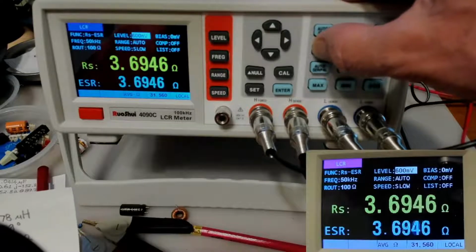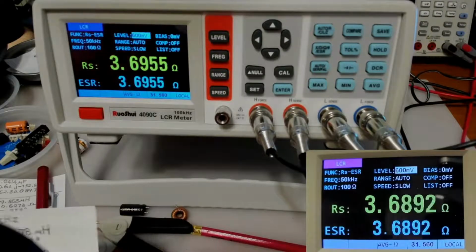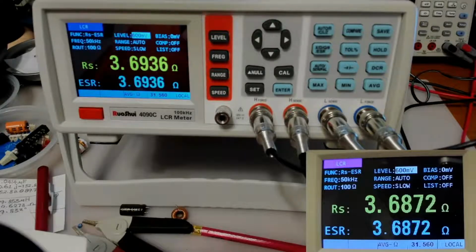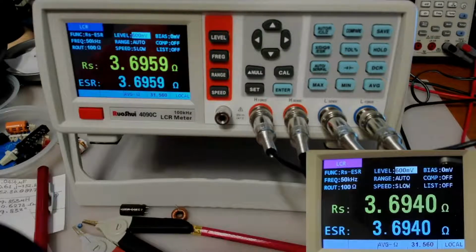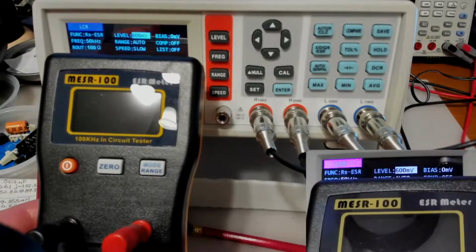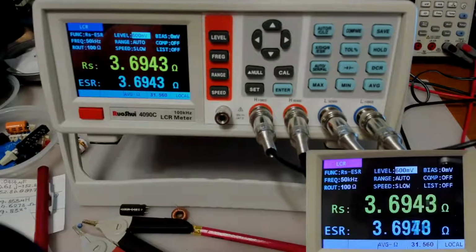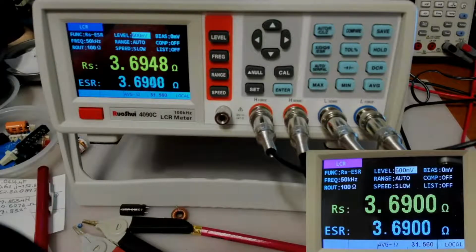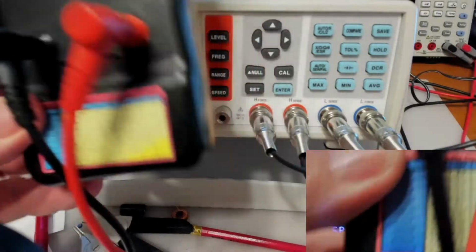Then we will also find out what they're calling ESR, or what the industry calls ESR, this magic value that people always tell you to measure on electrolytic capacitors. And in fact, remember, here is an ESR meter, that's all it does. It just measures the ESR, and this particular one tells you if it is good for a particular capacitor and so on, so that's kind of handy. There is a little table on it as well.